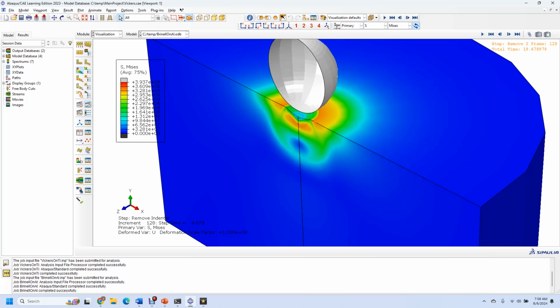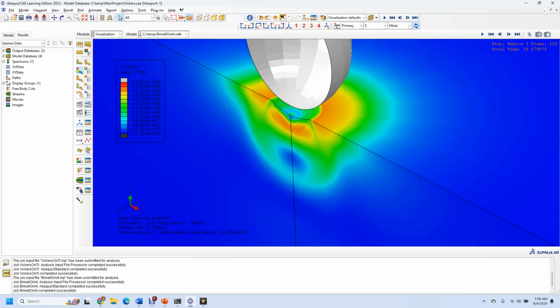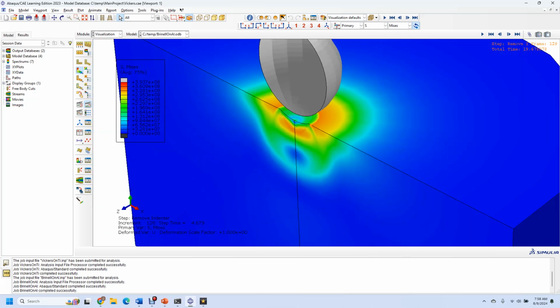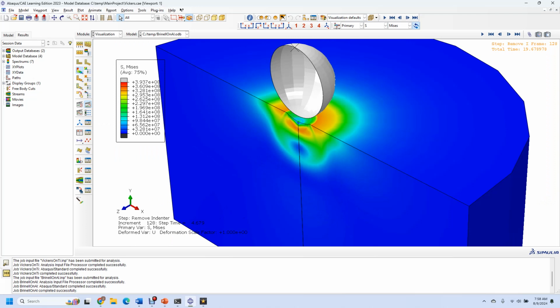Once again, here I picked this point, or one of these points, to measure the diameter. I measured the radius, doubled it to get the diameter, and then similarly got the reaction force here. And when I calculated these, I got a hardness for aluminum of 94 and a hardness of 312 for titanium on the Brinell scale.